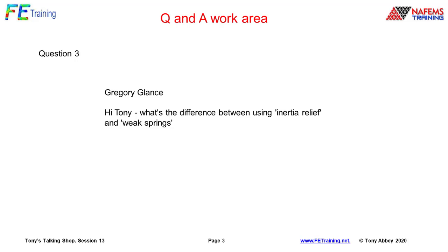But I think what happens is you're trying to pick weak springs to stop rigid body motion, and again, there are techniques where the system can actually apply weak springs. What it's trying to do is give you almost like a mattress, a mattress which is very soft, it's distributed throughout. So my outer balance force, instead of reacting hard at a single point, is reacted by a set of distributed springs, rather like a mattress. Think of something sitting on a mattress. I push a force into it.